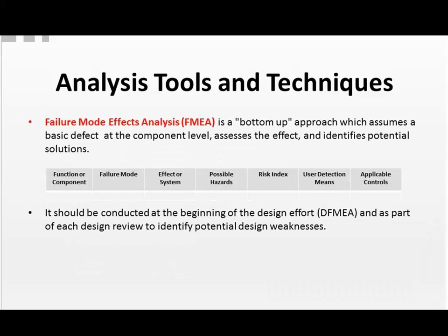Now, when a device contains many mechanical components, an FMEA should be considered. However, an FMEA is time-consuming and generally applied only to Class 3 devices or to the safety critical portions of devices. Now, for those devices that contain many electrical components, an FMEA is also recommended. It contains several headings. You have the function or component that would be listed. The failure would be the loss of a function under the stated conditions. The failure mode describes the way the failure occurs.